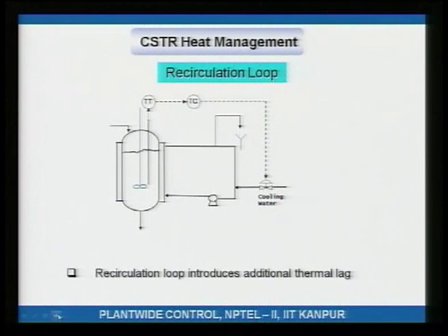Here what is done is you got cooling water going in right here, and you got a pump that is circulating the cooling water in the jacket at a high flow rate, and this flow rate is the same as this flow rate. So, the outflow or the overflow from the cooling circuit is the same as the inflow of the cold cooling water. Okay. What happens here is, you see, the circulation rate in the loop is constant and it is very high.